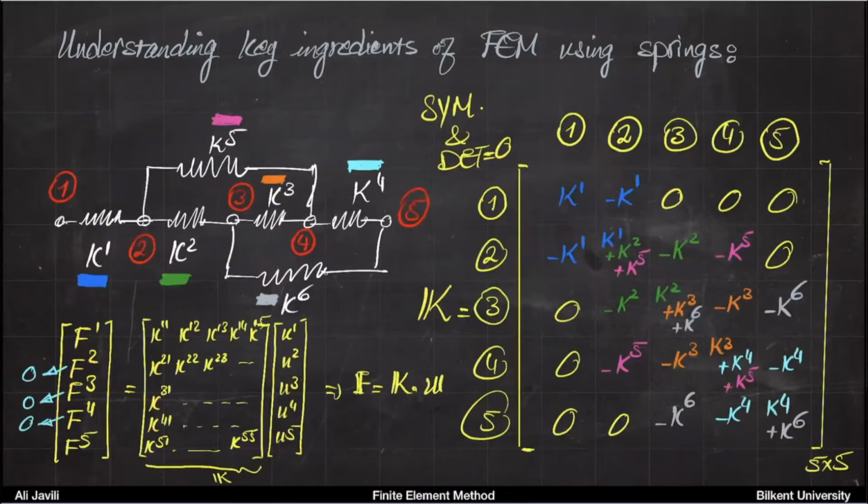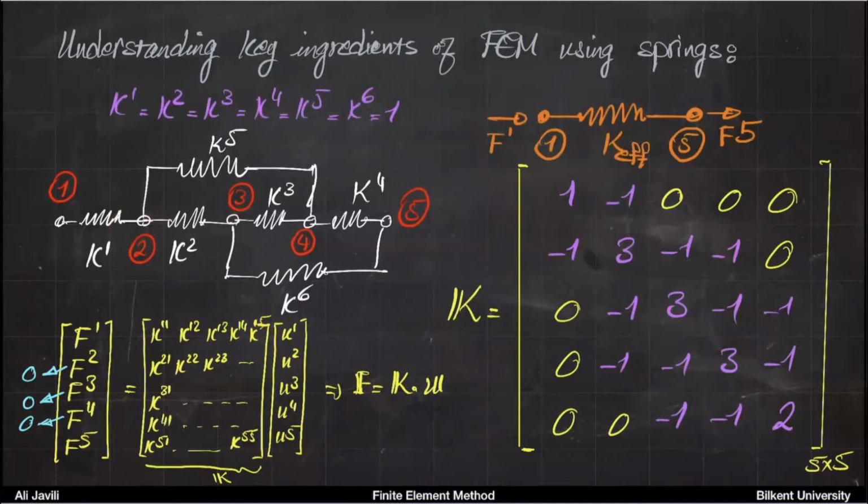Okay, and then we talked about a more complex system. We said, if you have a system like this, what to do next? Again, the process is formally identical. What we did was to write the stiffnesses for each of the elements one by one, and maybe you can identify these by the colors and so on. Then you add these elements together, or assemble them, and also impose the conditions that the forces are zero at certain nodes. By doing that, instead of a system with 5 unknowns, you would have a system with 2 unknowns.